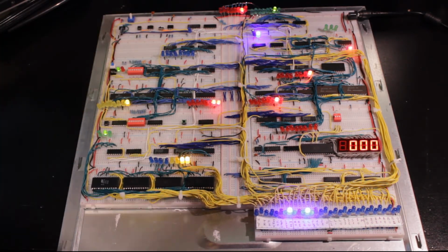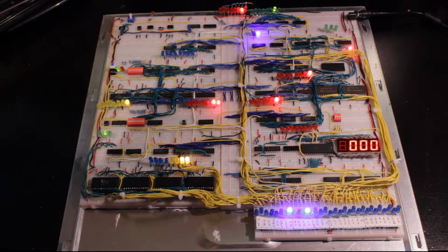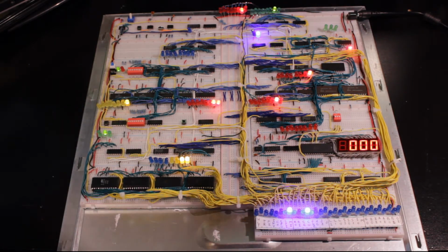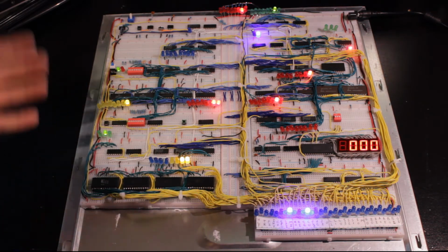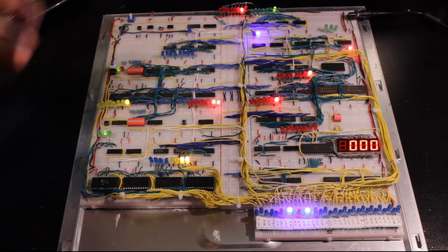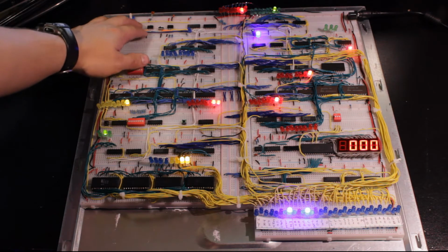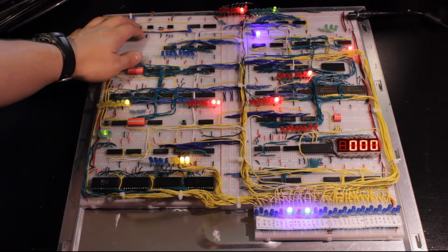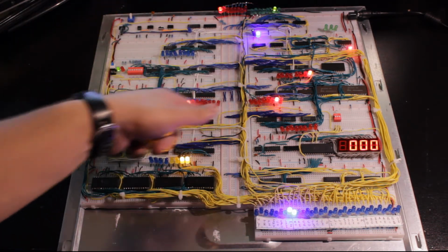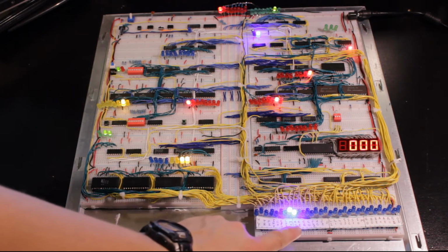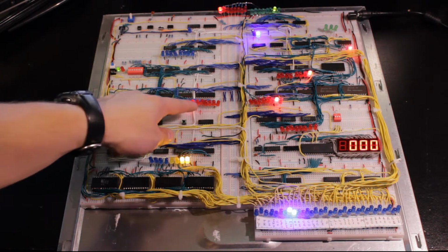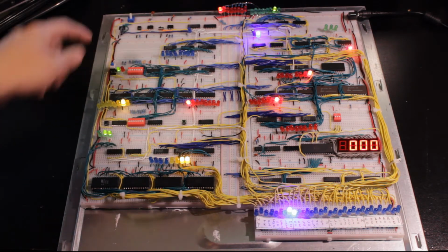Now we're executing the store A instruction for real. And the store A instruction needs to get a pointer to the location in memory where it's going to store A. So the first thing it does is fetch the next location in memory to use as a pointer. So we say counter out and memory address register in and go to 2. And now we have this pointer, the 0x80 I said we were going to use for the first variable. And then we take the memory address register in, the RAM out. So this value is going to go out into the bus and into the memory address register.